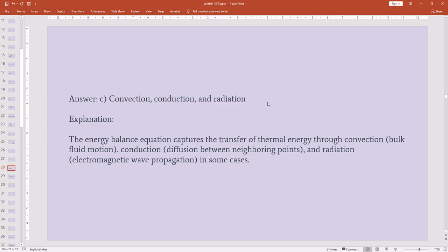When it comes to combustion chambers or very high temperature environments, we have to consider the radiation heat transfer occurring there. So we have to model radiation also, and we can model radiation with CFD. We take radiation as another transport property, a radiation transport problem.